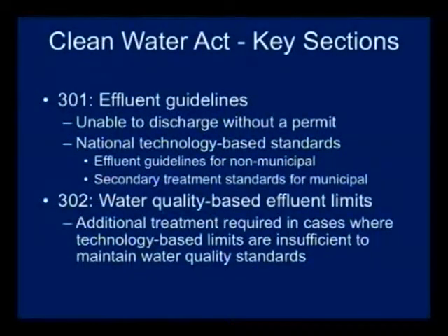Every industry has a categorization. If you're in a certain industry, there are minimum levels of treatment that you have to provide. Steel plants have their specific regulations. They're working on them for aircraft de-icing. Each industry has technology-based standards. For municipal wastewater treatment plants, the standard is what's called secondary treatment. Won't get into the environmental engineering, but you need to provide more treatment than just settling the solids out of the water. So anybody that gets a pollutant discharge permit has to meet a technology-based standard at a limit. That's the bare minimum of treatment that everyone has to provide.